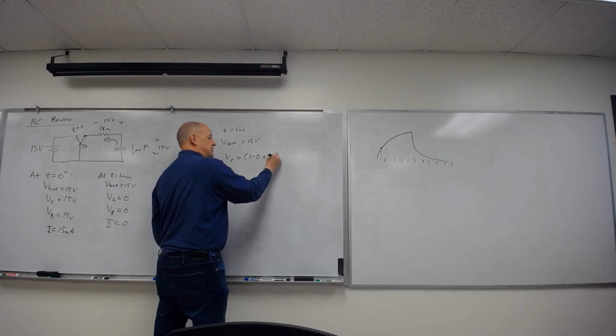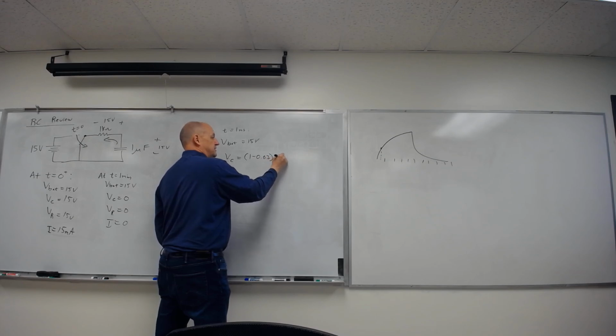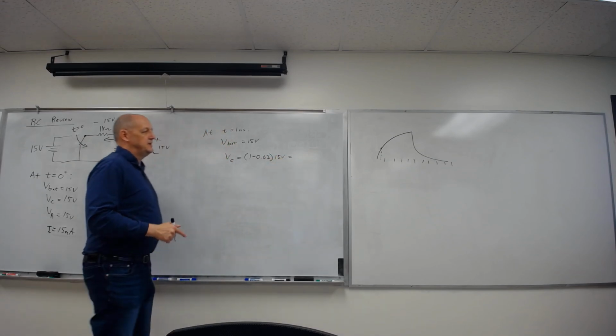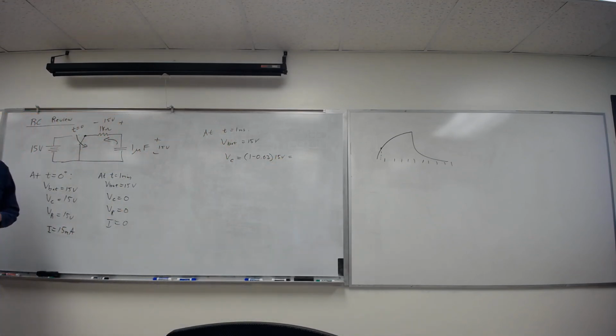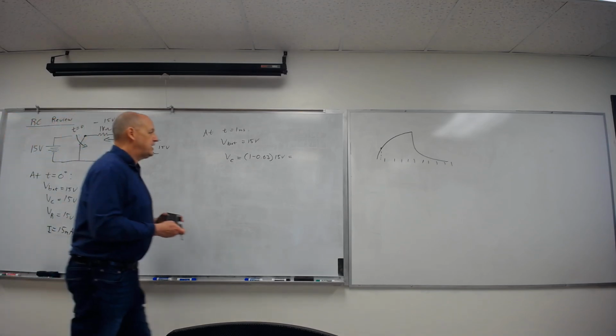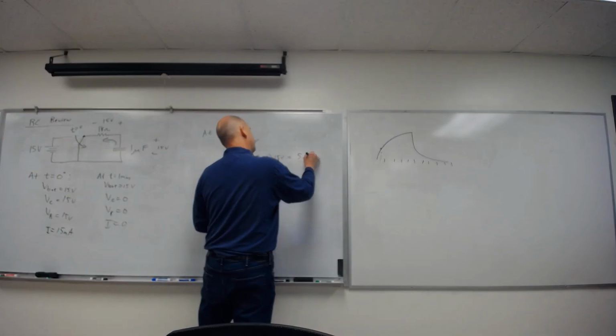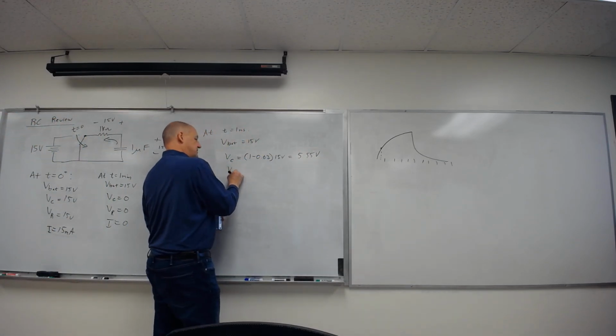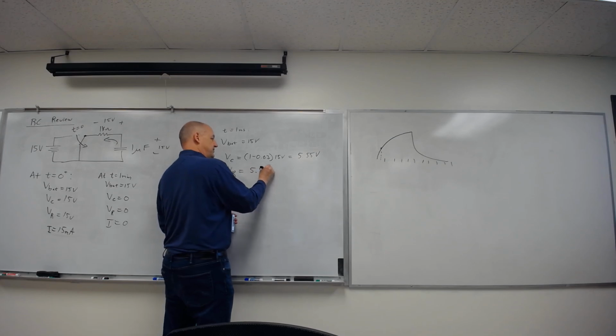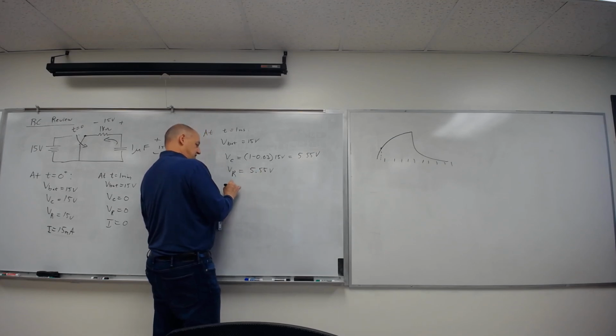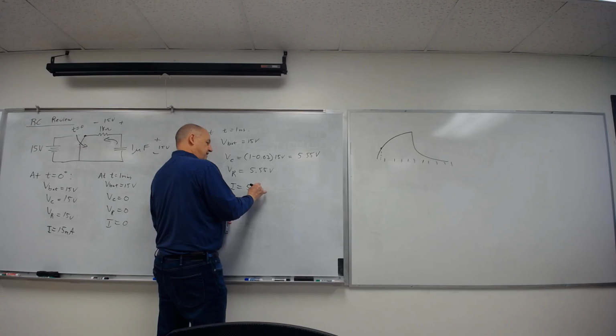or that was 63%. They'll tell us over there, what is that, 37%? Because it's gone 63% of the way down. So we'll actually be at 37% of its initial voltage. So we'll drain all the way down to 5.55 volts. That means the voltage across the resistor, since it's the only thing that can be dropped in that voltage, is 5.55 volts. Therefore, the current is 5.55 milliamps.